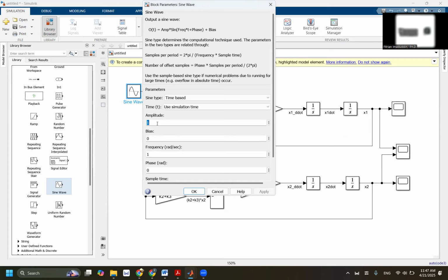So if I have a system like this, it is different. Previously, x1 meant I was shifting the position of m1 1 centimeter to the left or 1 centimeter to the right. That's x. X means displacement. But if you talk about F, you're talking about force. If you have a sinusoidal force, you cannot really predict the motion unless you calculate the static deflection. But basically, what you're doing is pushing the mass to the left and to the right harmonically. You don't care how far it's moving, because what you're doing is pushing.